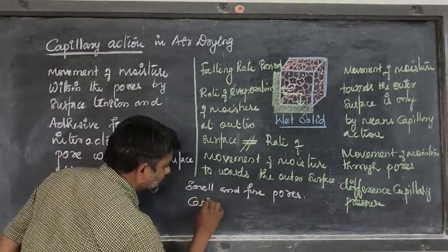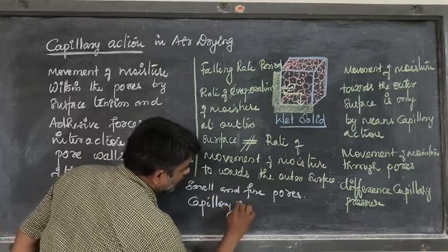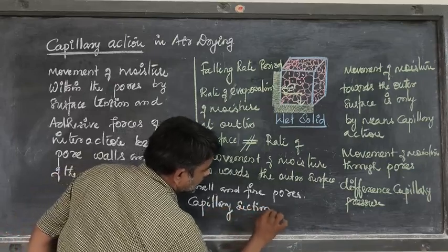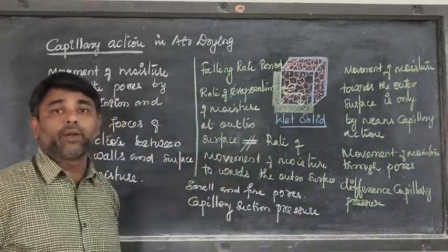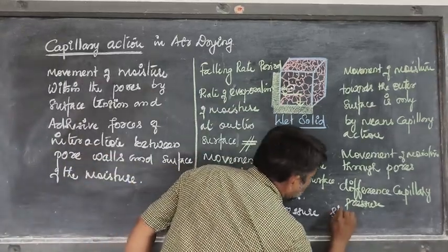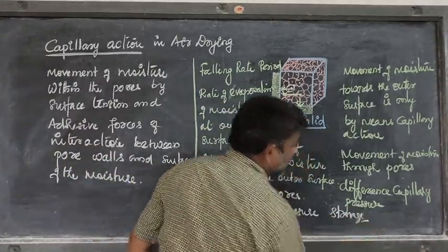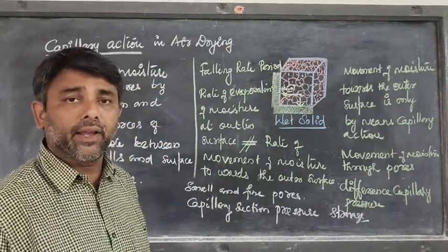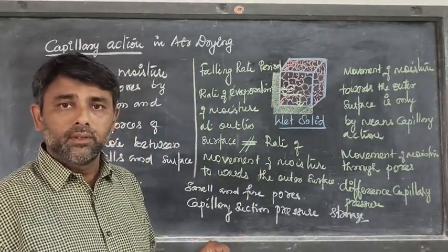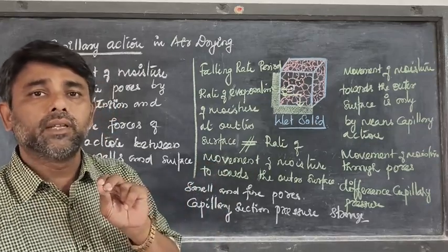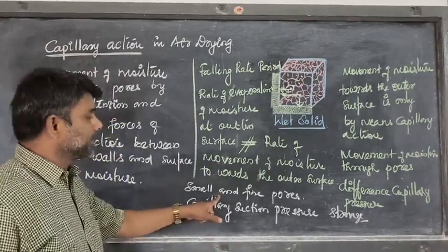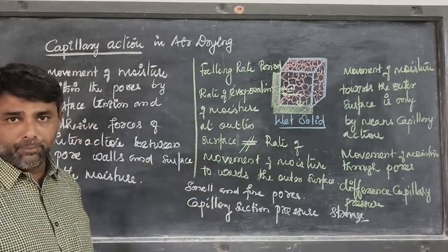Capillary suction pressure will be predominant, will be strong suction pressure. Clear? For small and fine pores, the capillary suction pressure will be vigorous or very strong. Clear? This is the case in falling rate period.